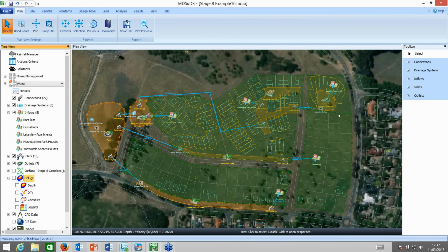And there's our completed model. So we've connected the bioretention area into a porous car park. This now is connected through to another bioretention area that connects into a pond. And we have another system coming from this little grassland area, runoff from the highway here, from the street, coming down through into the pond. And then we have the properties here discharging into a swale. And the flow into the swale doesn't need to be point flow. We could also have sheet flow coming in, lateral flows coming into the swale as well.